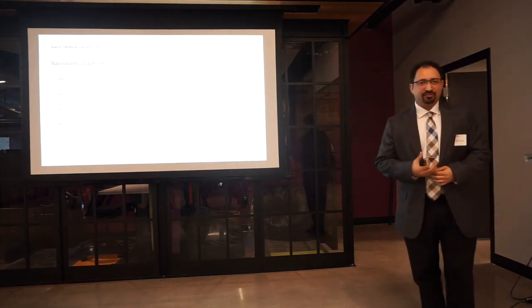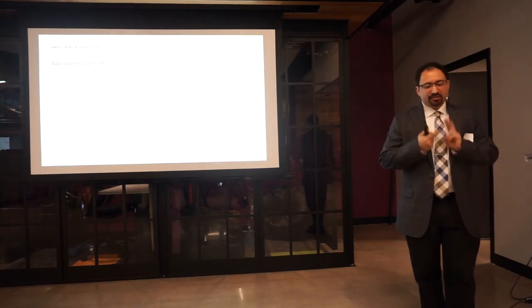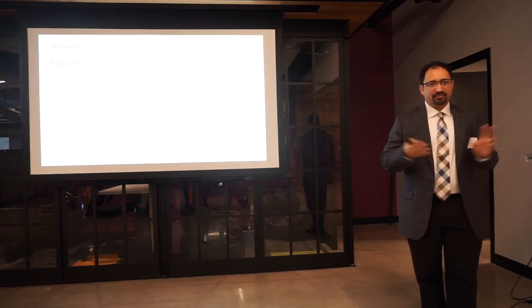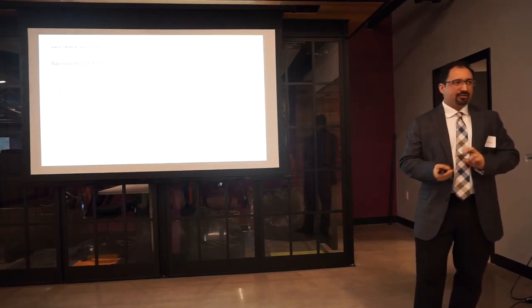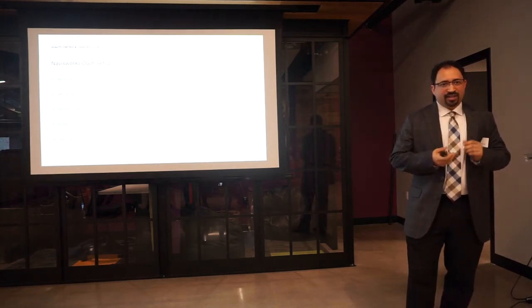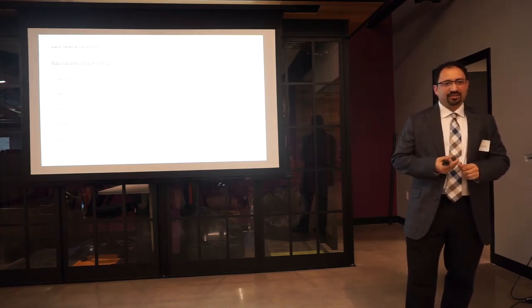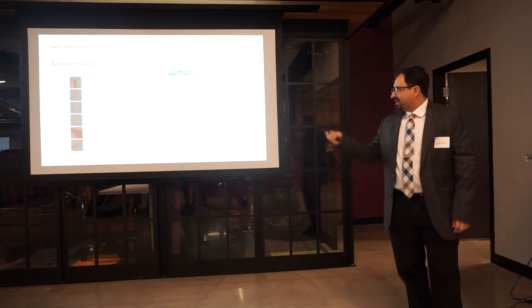Once you bring it into Navisworks, you can set up every single layer. You use work sets in Revit all the time. You can use those same exact work sets as your layers for Navisworks. So you set up the mechanical, the structural, the electrical, all these different layers, and you can test them all and figure out what is interfering with what. You set the tolerances, and you generate a report. A sample of that report is right here.